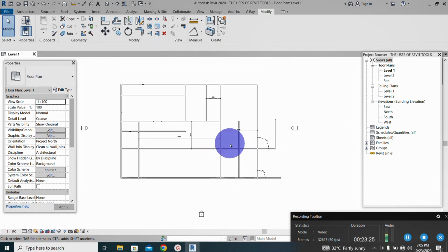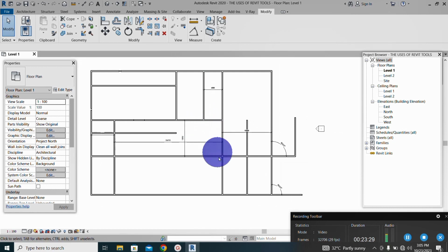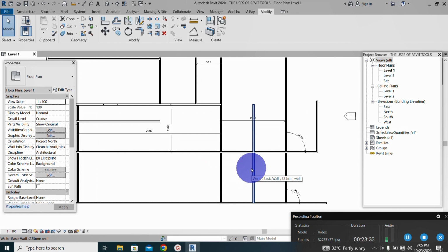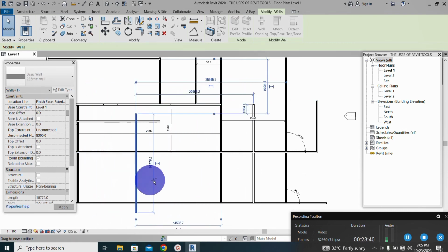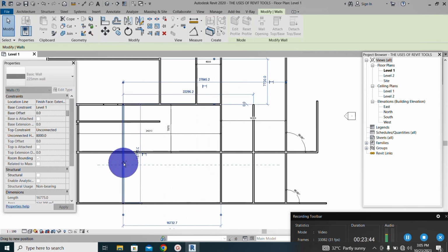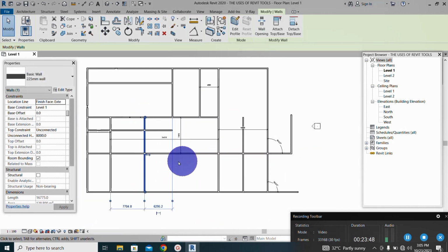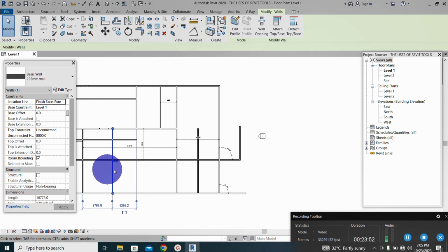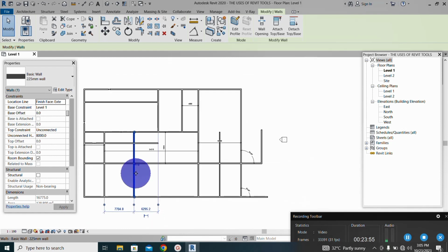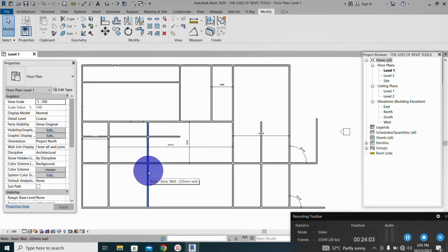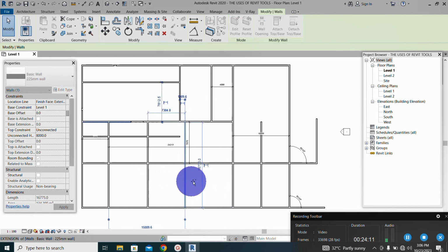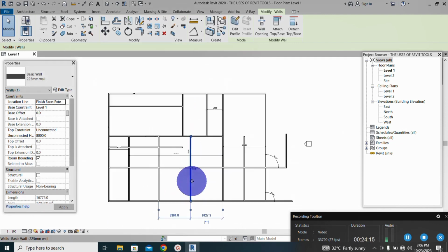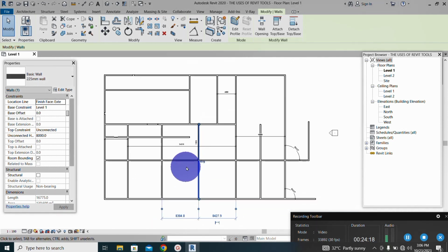Another way you can copy now is by clicking on your control button on your keyboard and drag. You press your control, you click the object, you can see. With that, Revit allows me to copy. Let's assume I want to drop it here. You can see this particular object still remains there. Then this is the new one I just copied. Let's exit this command. You click on the object, press your control, you drag. You can see, then you drop. That is copy for you.